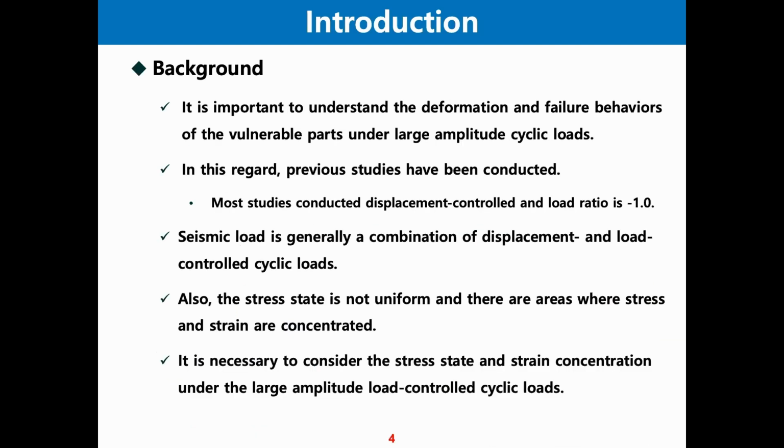So for reliable structural integrity evaluation, it is important to understand the deformation and failure behavior of the vulnerable parts under large amplitude cyclic loads. In this regard, previous studies have been conducted, and most studies used displacement control with a load ratio of -1. But seismic load is generally a combination of displacement and load control cyclic loads.